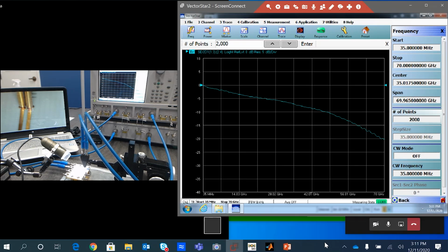And as I said earlier, you want a long arm on this thing. And then this is connected to the probe. Now this is the true differential 70 gigahertz probe. And it's controlled by these controls back here, your X, Y, and Z. And this one here is your planarization control. If the probe tips are not planar to the test pad, you're not going to make good measurements.